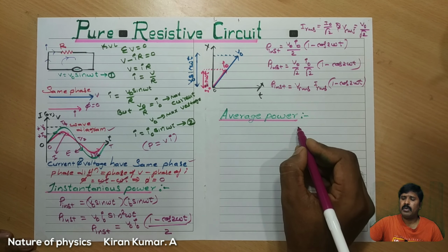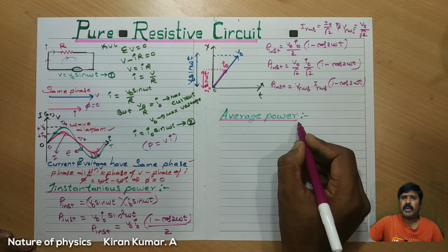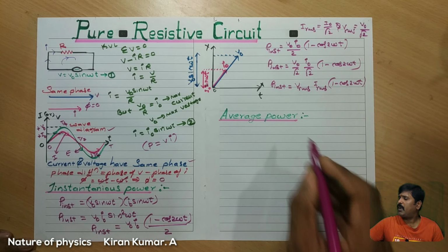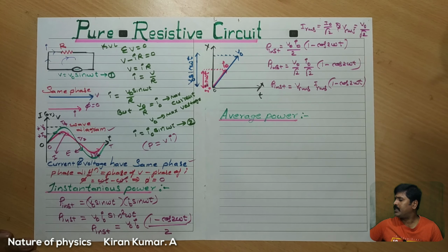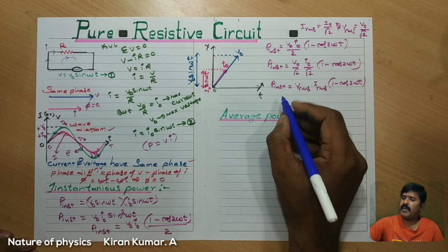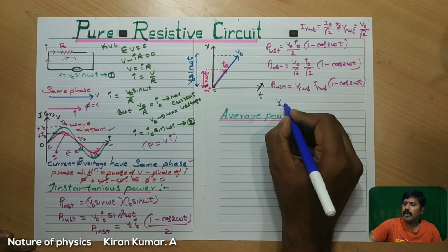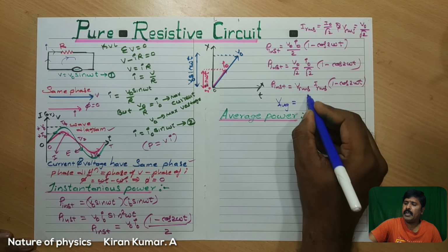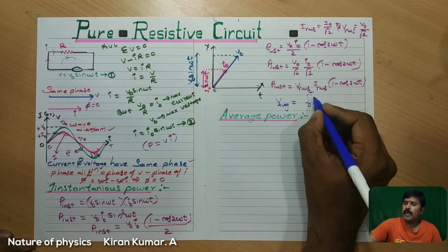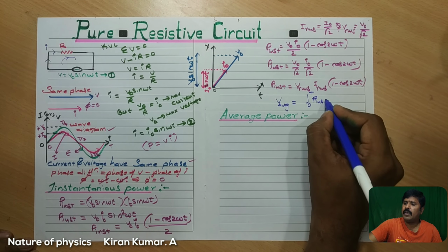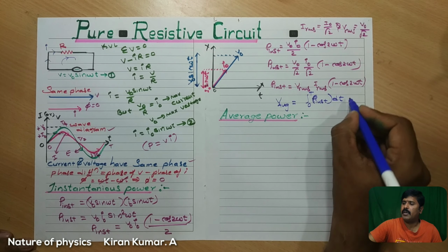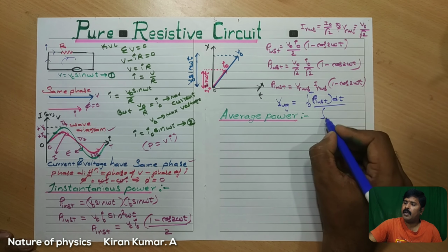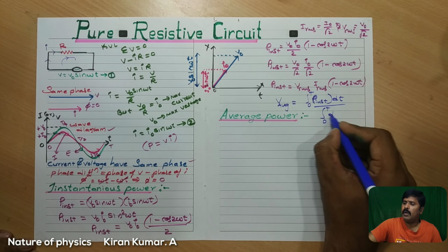Okay. This value we will replace in the average power, student. Look at the board. So now average power, I am going to write the basic formula for the average power. Here I have a space, that's why utilizing this, student. Okay, see, P average is equal to integral 0 to t P instantaneous power into dt, student, whole divided by integral 0 to t into dt.